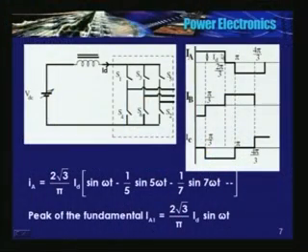We had assumed that the DC link current is constant and ripple free. So the phase current or line current flowing out is also constant and ripple free. What is the harmonic spectrum? We had a line to line voltage waveform, almost the same for the VSI.